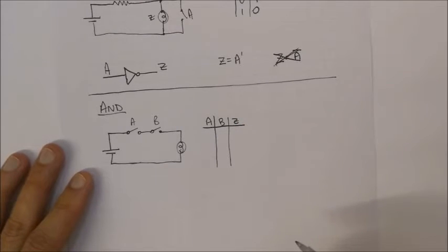I know that a lot of people would go and find some pattern, or they'll try and write things down. My advice is always count from 0 and onwards up to the end, because the value 0 is often forgotten in the truth tables, and also it allows us to make sure that we look at all possibilities.